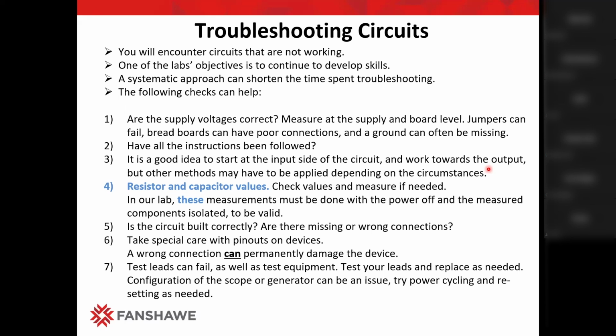Depending on which way you want to start, if you're troubleshooting maybe some kind of audio mixer or audio amplifier, you can start at the end and look for where you begin to see the signal in the circuit. So you go backwards, or you can inject the signal and follow it and see where it stops. You can work either way, whichever suits you and is the better method for that. So there are some names: signal injection or signal tracing, or signal injection and tracing, right?